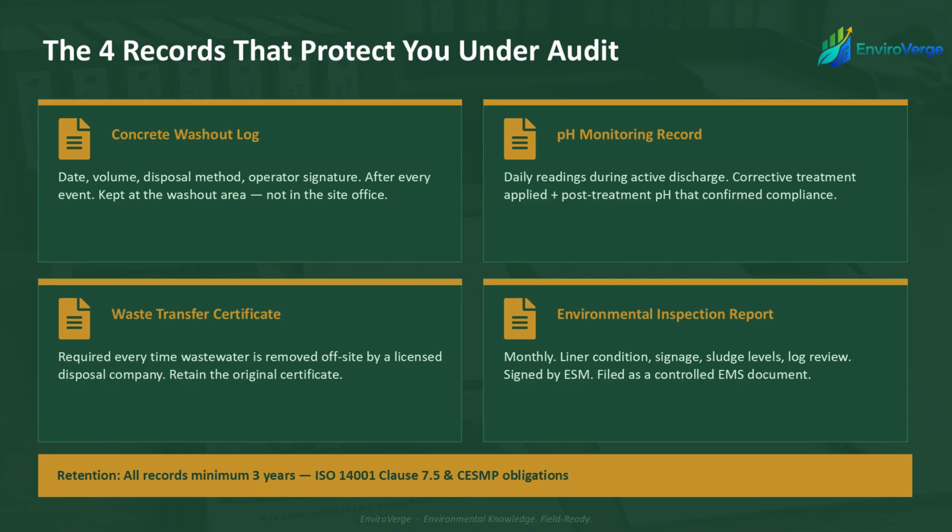Second, the pH monitoring record, a separate daily log capturing all pH test results taken during the discharge decision process. Each entry includes the date, time, pH reading, meter calibration reference, and any corrective action taken, including the post-treatment pH that confirmed compliance before discharge.